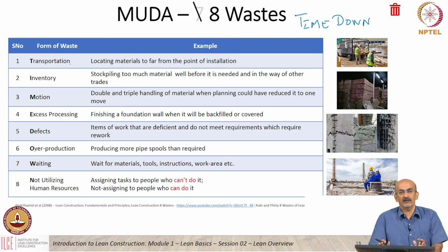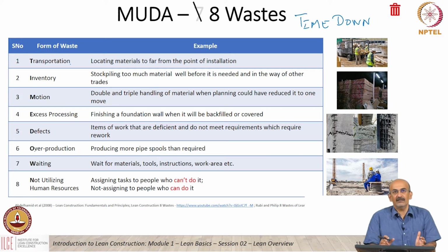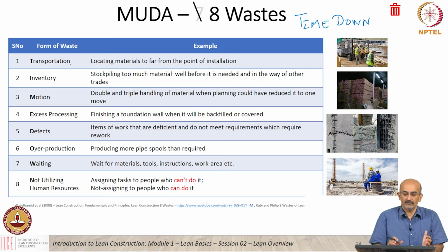Even a half finished product, let me say it is an apartment building where I have several apartments that are partially finished. That is also my inventory of apartments, it is partially finished, it is not sold to the customer, it is also waste. I could have motion waste where it could be a rebar yard and people are doing a lot of motion unnecessarily, and it increases the time it takes to do the rebar activity, that is also waste. Excess processing, either finishing a foundation wall which is going to be backfilled or covered, or doing high tolerances where the tolerances are not required, is excess processing.